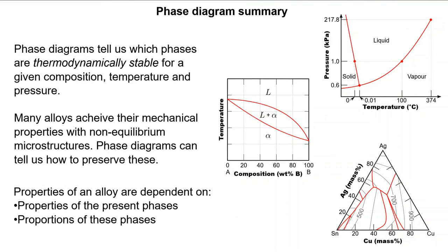Where I got up to in the last part was explaining why phases are important and the basis for their existence thermodynamically. I covered their premise, that they can be unary, as if they will describe a single component over variations of temperature and pressure, or multiple components with pressure constant and temperature varied, binary for 2 components and ternary for 3. Like I said before, we're only going to stick to binary systems in this course. And these are important because they inform on properties of the various engineering alloys available and their provenance.